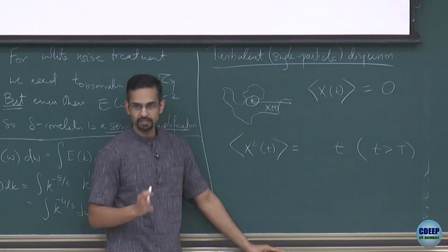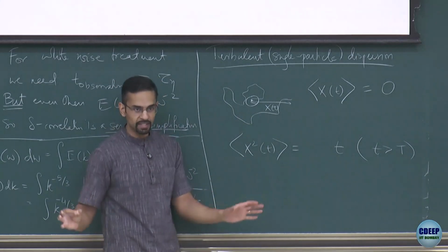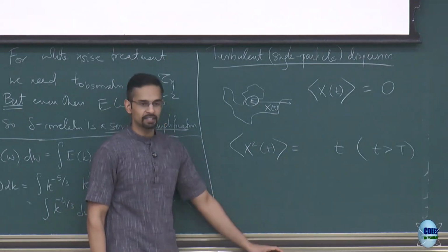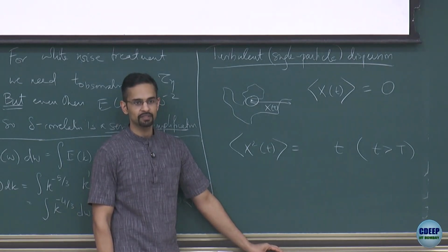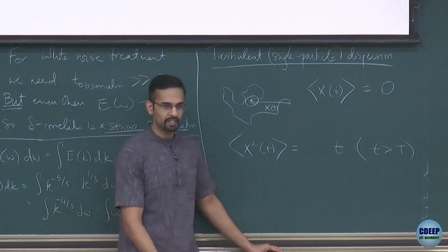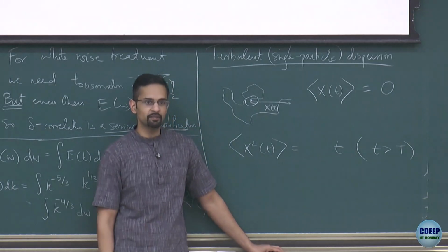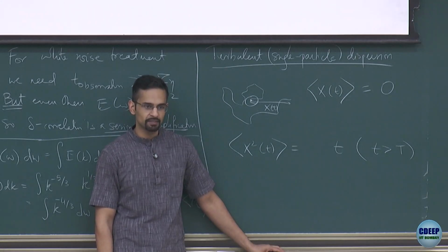This is purely based on a physical argument, where you think of the flow as a bunch of large eddies, and all these large eddies are uncorrelated. But what would be the diffusion coefficient of this kind of effective Brownian motion? How do you think of diffusion at the molecular scale? You say that I have some velocity of motion and some mean free path, and their product gives me the diffusion coefficient, in meter square per second.